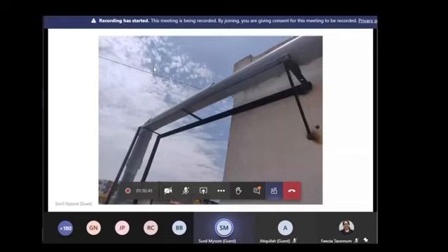If you give some cognizance to the details, the pipes start from 4 inches, 6 inches, and then go to 4 inches. Vertically you need a lesser cross section, while horizontally you require more cross section, because vertically there is greater slope available. Because of surface tension, the water never actually falls in full. If you take the cross section of the pipe, it may be half or 3/4, in most cases less than half. So you reduce the cross section predominantly to save the cost.